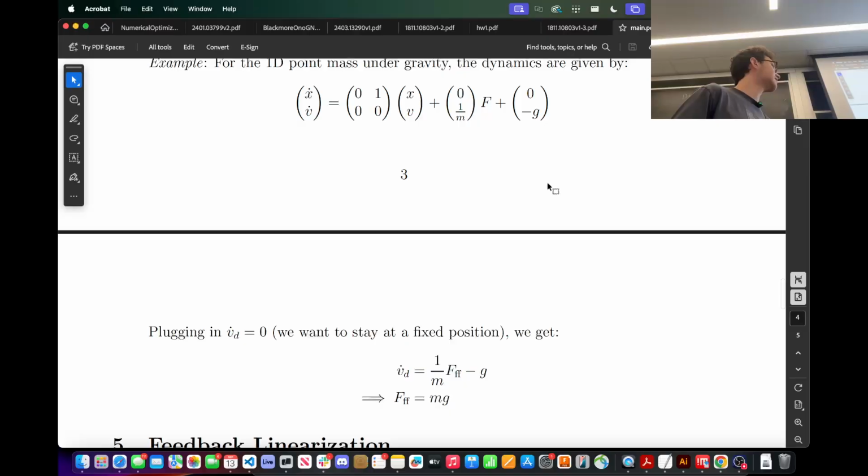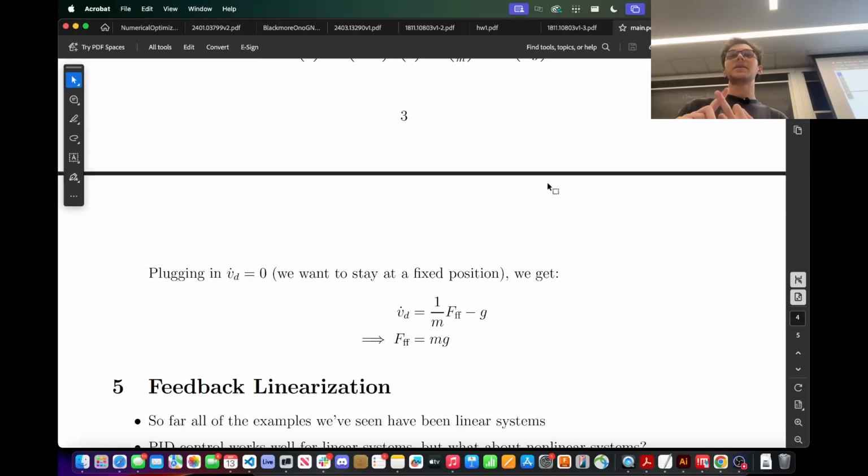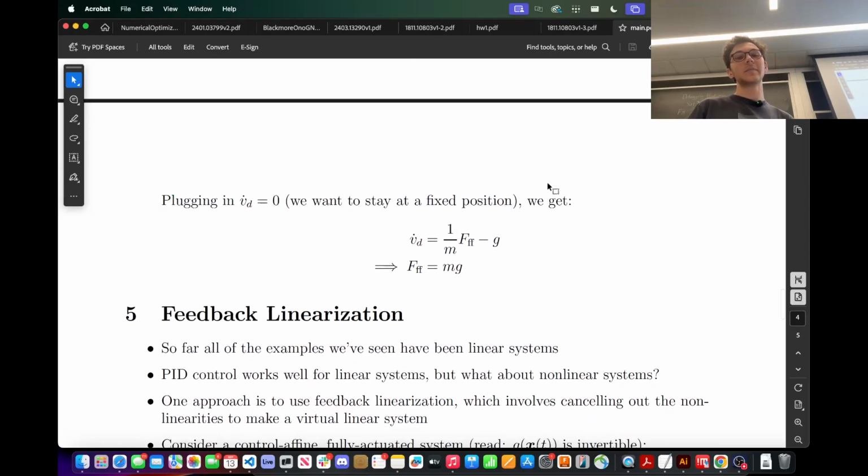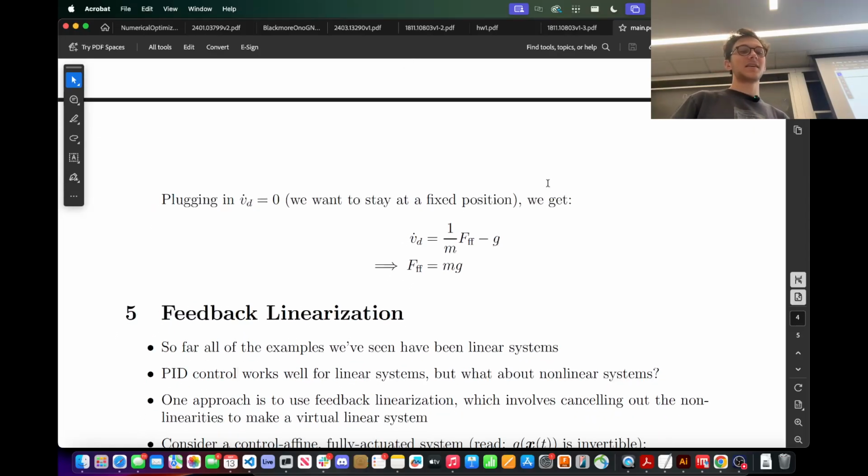Cool. Okay, so we've seen PID plus feed forward. And now the final step in using PID to do a lot of things is feedback linearization. This name should hint at what it's going to do based off of the example that we just discussed: if, by applying the right control input, I can make my system look like a linear system, then I can apply PID to it, and it will behave very nicely. Even if the system is actually nonlinear, the original system can be nonlinear.